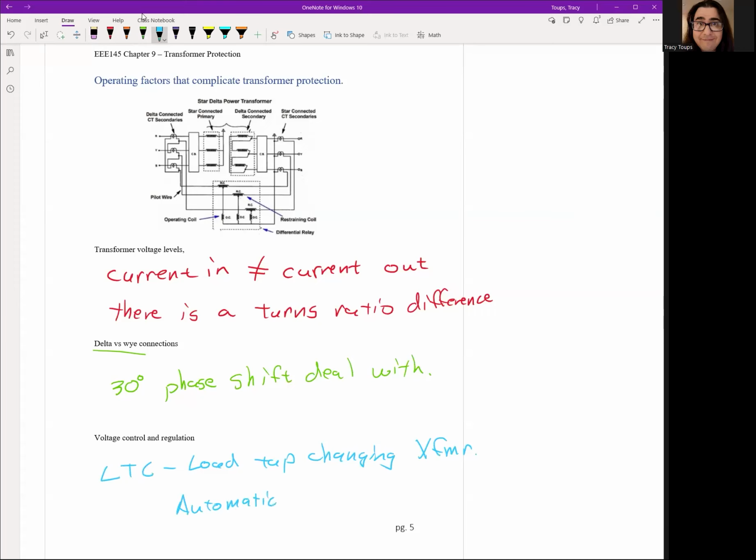And just to give you the 30-second version of it, a transformer typically has a hard turns ratio that's wired in, but we could put an LTC to change the tap on the secondary side and ultimately change the turns ratio. So it can automatically change the turns ratio. And the limit is typically plus or minus 10%. It's not that much, right?